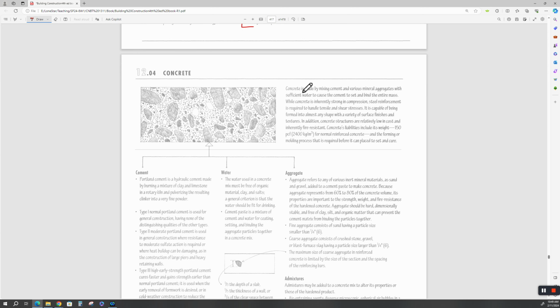Now, if you take a bituminous coal, like from a coal-fired power plant, or volcanic ash, that's a super-duper pozzolan. Back in the late 70s and early 80s, we used to substitute a percentage of the cement in the reinforced concrete with the fly ash from the coal-fired power plants, so they wouldn't have all this fly ash left over.